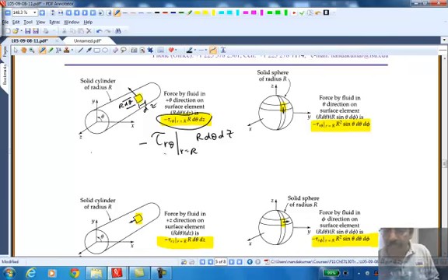What do you remember about the first index and the second index of tau? First index identifies the surface. The second index identifies the direction in which the force acts. That stress has 9 components in all coordinate systems. We saw Cartesian, the same thing applies to cylindrical, same thing applies to spherical coordinates. That tau is a physically meaningful quantity. Its components will be different. So in this case, what we are saying is, I'm going to calculate the stress on an R surface. Constant R surface is a cylinder. We already know that.